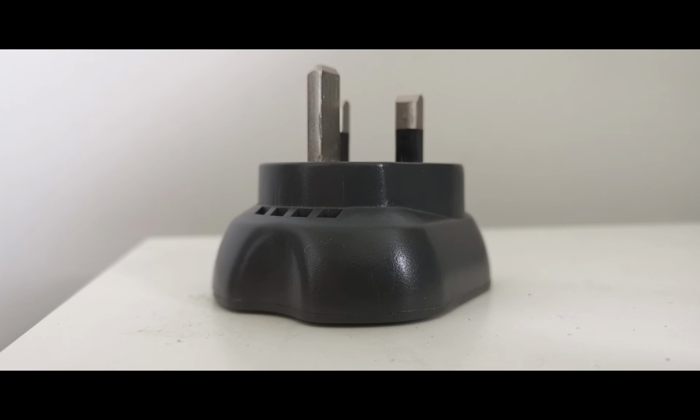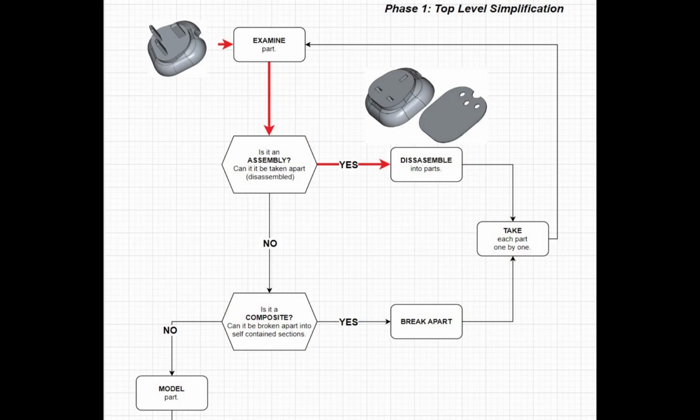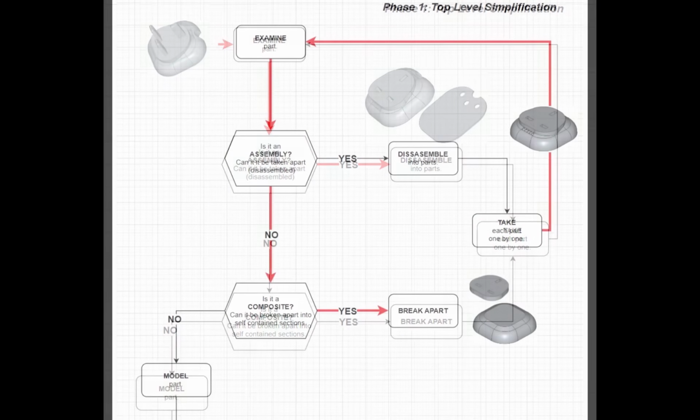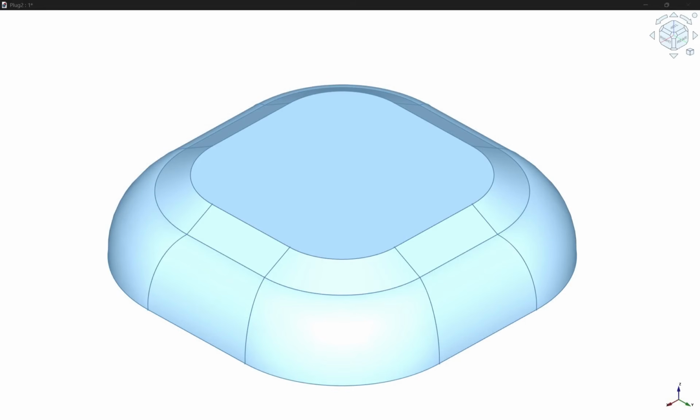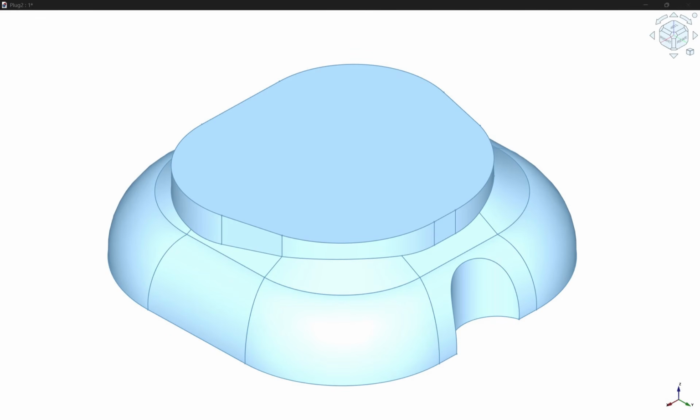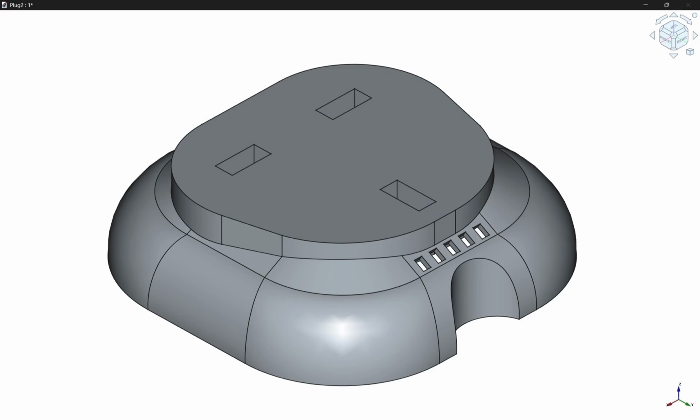Before we begin this project, let's analyze a few workflows. If you've been following along with the previous videos, you'll understand that we begin with a simplification process. The Part Design workflow in FreeCAD requires us to create initial features and then extend those by adding subsequent features on top of the previous one. Simplification, however, works in reverse, removing features to identify the core form to determine the necessary operations. In this case, we eliminate the finger well, the top pockets, and in some instances, even the internal hollow. This allows us to visualize the fundamental shape, which looks something like this.